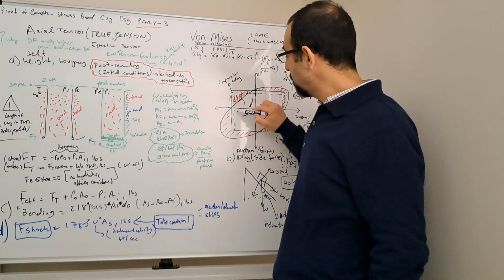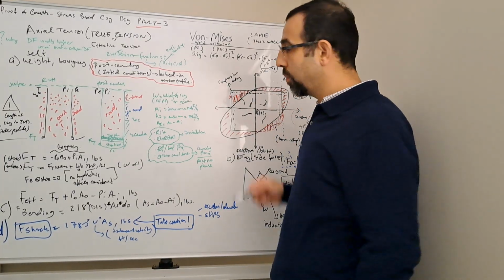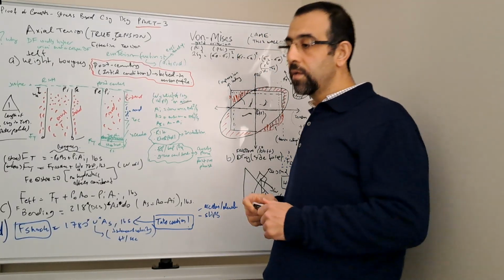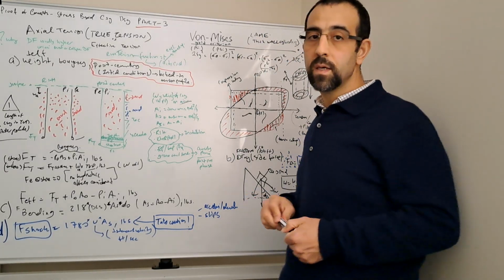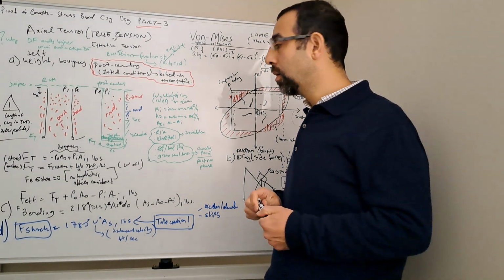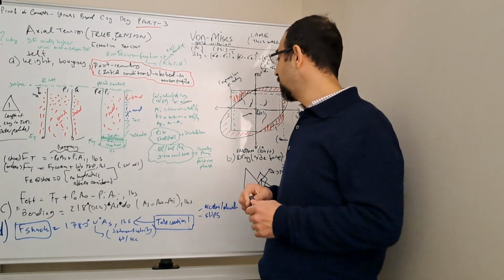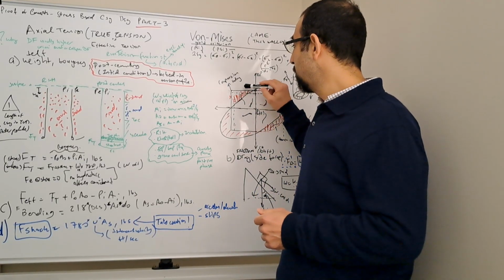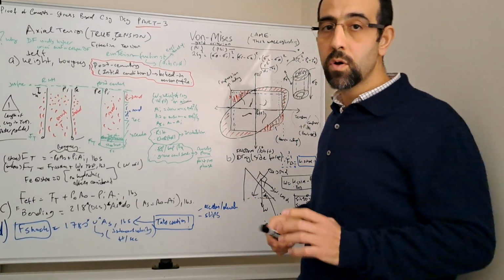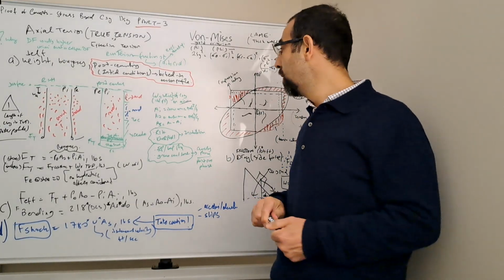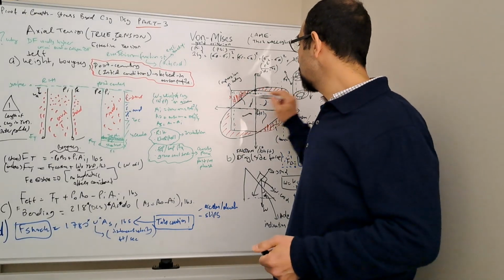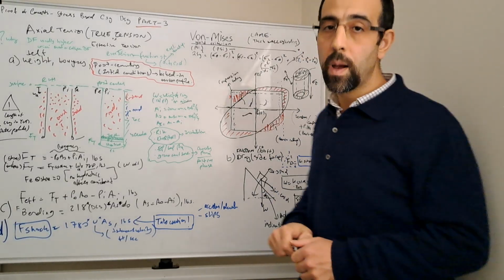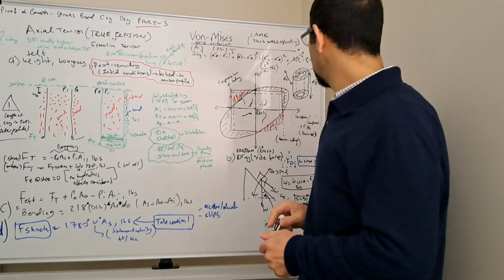Another thing to mention here is these dash lines. For example, if you need a special clearance pipe, let's say you need oversize casing, 11 7/8 or 14 inch, then usually the performance ratings of the burst and the collapse are the same. However, your compression and tension performance ratings are smaller in the connection compared to the pipe. So that is one thing to take care of.